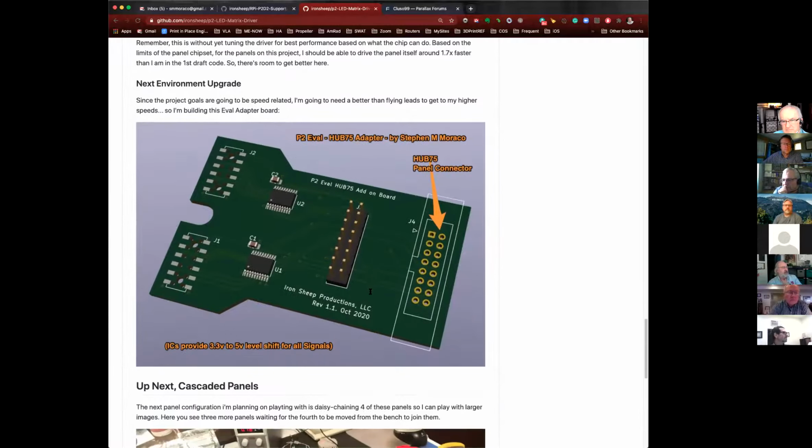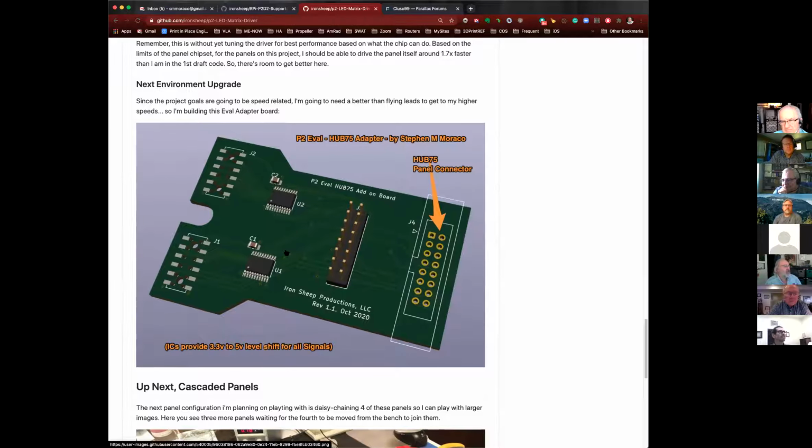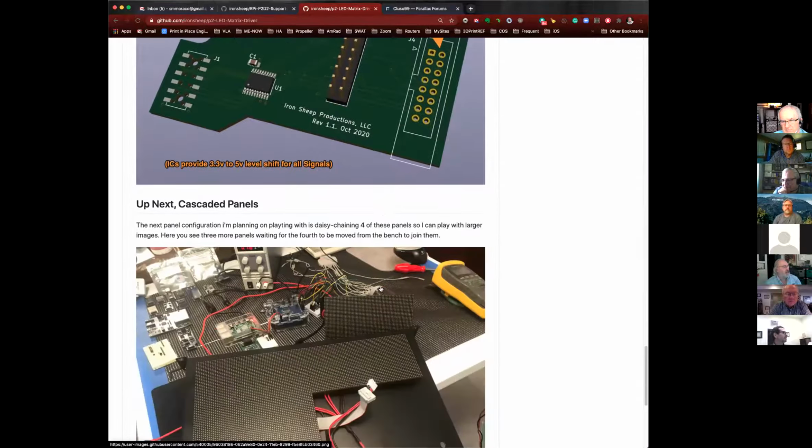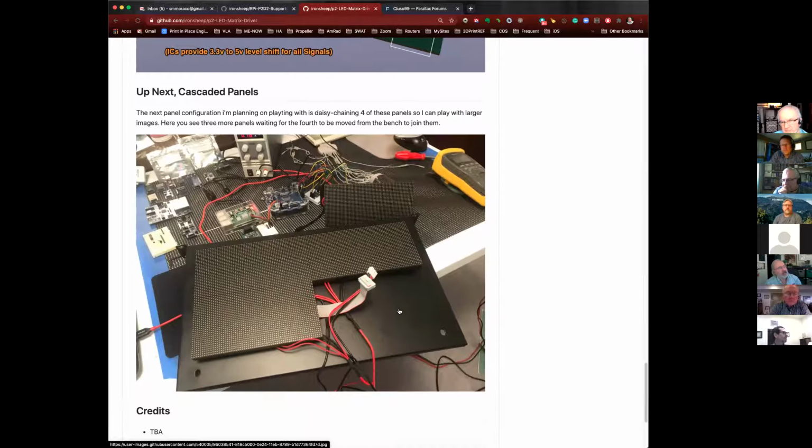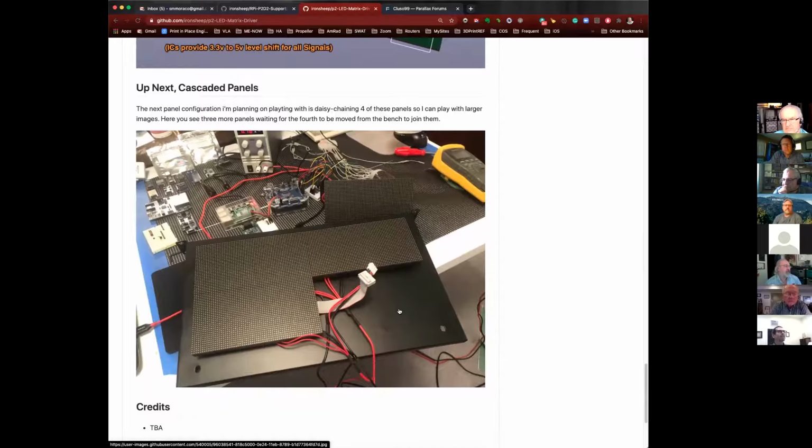And so now I have this that I put together, and there's no way I'm showing you my layout details, Ray, because I'm just a hobbyist. I'm not at all professional on this, but at least you see me pretending a little bit. These are nothing more than level shifters, logic analysis connector, and the Hub 75 shell connector that's male pins, and then our adapter here. The goal then is to drive, here's the one panel under test currently. I'm going to gang them together into a 4x4 and then see if I can make the driver do that. So that's really my project.